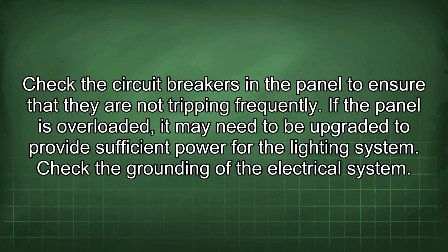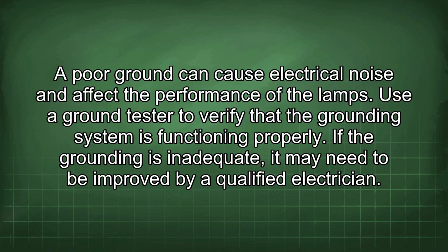Check the grounding of the electrical system. A poor ground can cause electrical noise and affect the performance of the lamps. Use a ground tester to verify that the grounding system is functioning properly. If the grounding is inadequate, it may need to be improved by a qualified electrician.